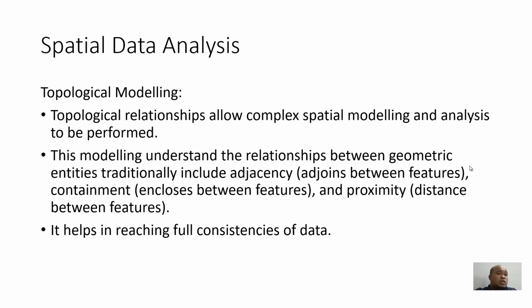Next is the topological modeling. Topological modeling is a very powerful tool. It helps you a lot, right? So topological relationships allow complex spatial modeling and analysis to be performed. This modeling understands the relationships between geometric entities, which traditionally include adjacency, meaning the adjoins between features, the containment, the enclosures between features, and the proximity, distance between features. So it helps in reaching full consistency of data.